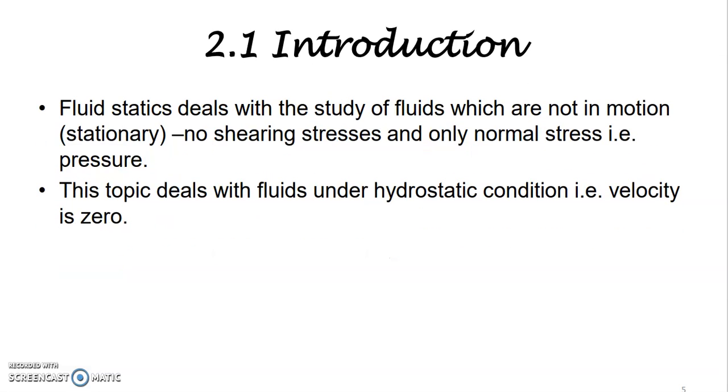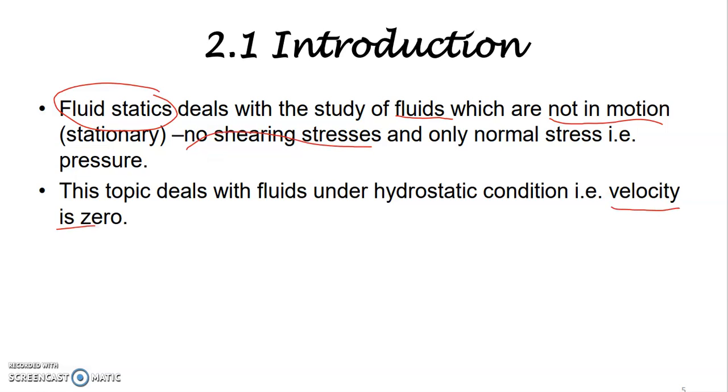Okay, as the introduction, you need to know about fluid statics. Fluid statics deals with fluids that are not in motion, meaning no movement, or we call it stationary. When the fluid is static, it means that there is no shearing stress and the velocity is zero. What pressure is involved? It is only normal stress.